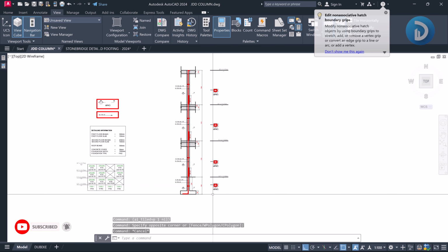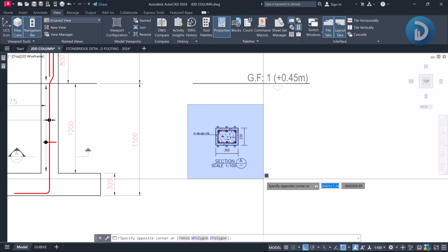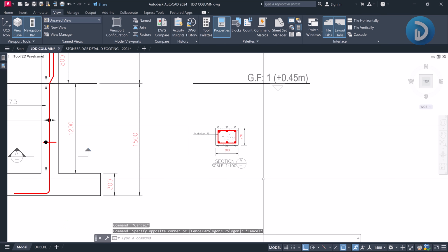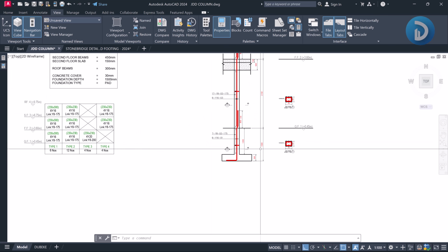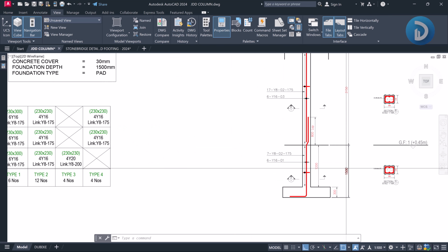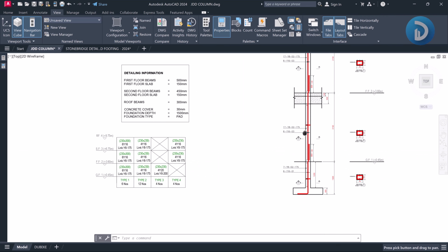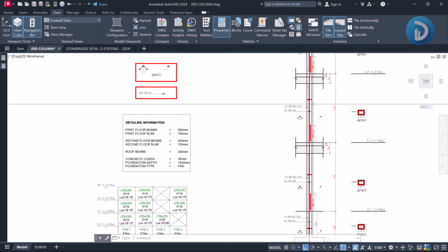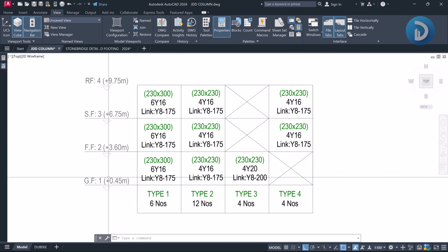While the second drawing that will come with your columns is your column section drawing. Okay, so these two drawings are vital for you to have an effective detailed column. So to run over the concept of this column detailing, as you can see over here, we introduced the different levels, which was the foundation level having a depth of 1.5, and we also introduced the ground floor level, the first and the second, making due regards to the difference in the story height.